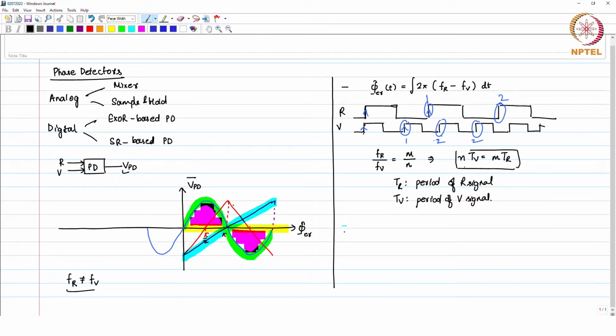So, previously in the PLL where we use the phase error detector, PD and loop filter, right, with VCO. The loop filter was type 2 loop filter and so on. The PLL was type 2 PLL, and in this particular case, the assumption we had was that initially we had the frequency error. Based on the frequency error, we will get VPD, and this VPD gives you control voltage output, which gets filtered, and you recover the frequency error.